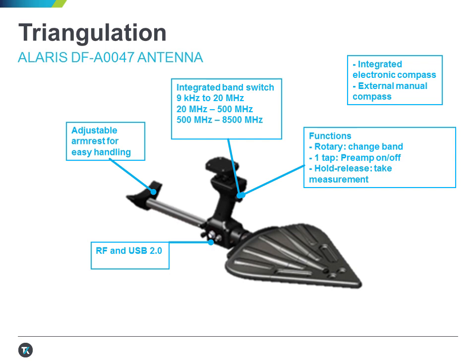When dealing with direction finding antennas, we have to be very careful with the type of antenna we're using, as well as what kind of active components might be in the antenna itself. In this example, we have an antenna with 3 different preamplifiers built into it. It's important for us to be able to turn the preamplifiers on and off, particularly in a dense urban environment, because very often there's so much RF energy that the antenna amplifiers themselves can be easily overloaded.